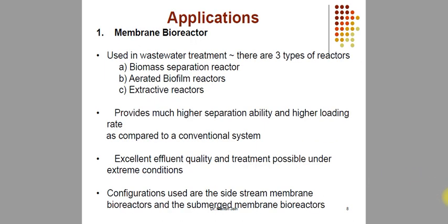Now the other classification of membrane reactor is the side stream membrane reactor and the submerged membrane reactor. It will come basically under the bioreactors. So first we will discuss the bioreactor. Actually, membrane reactors have very good advantages in the biological field. How? Because in the biological field we generally need to separate out the products from the reaction. In the biological reaction, a lot of unwanted products are produced during the reaction, and they should be removed from the reactor, because those products also work to suppress the reaction.